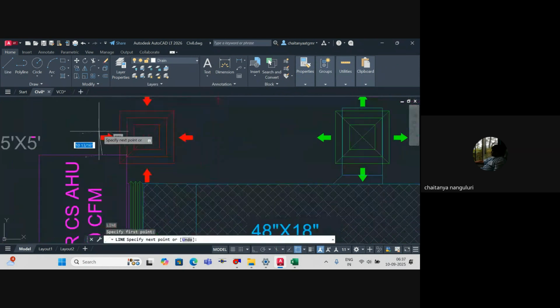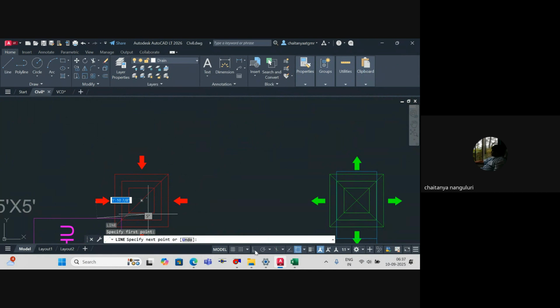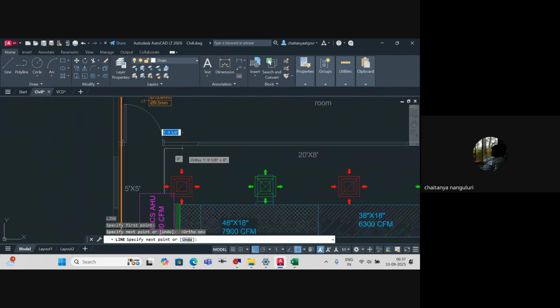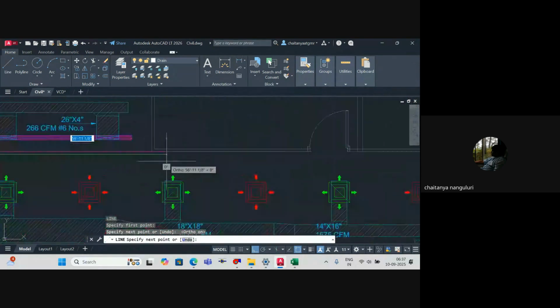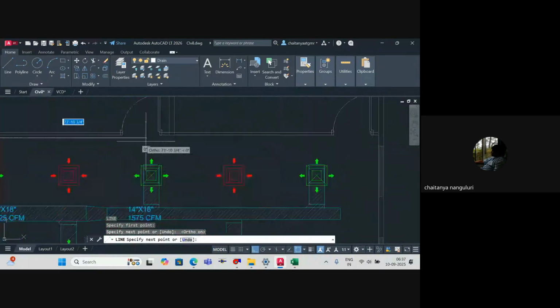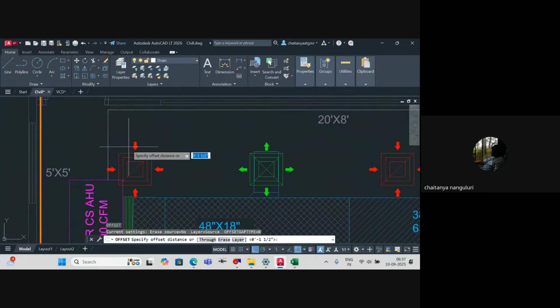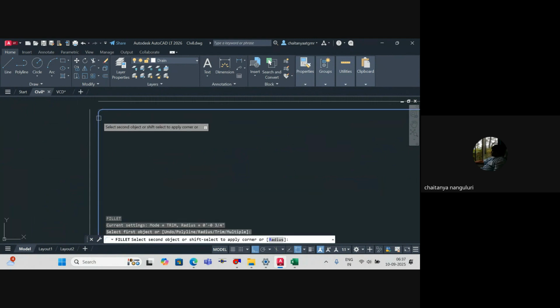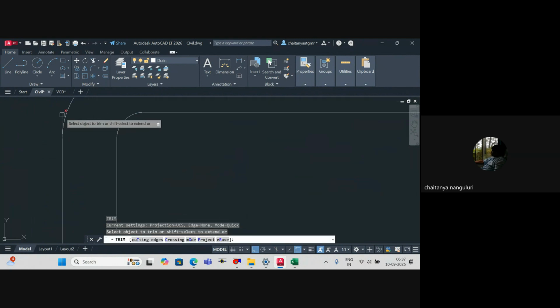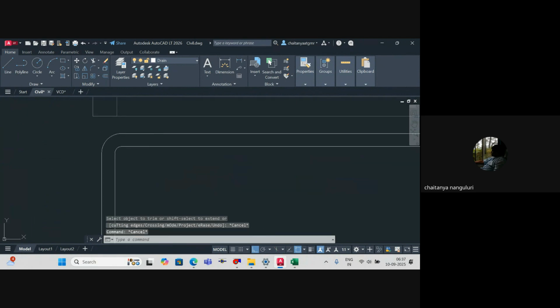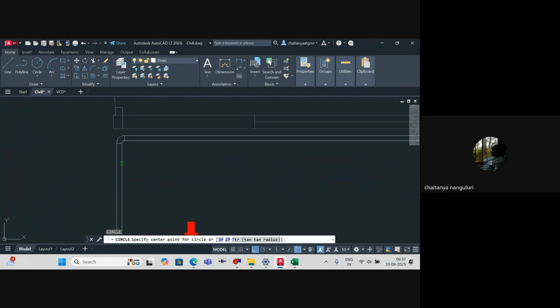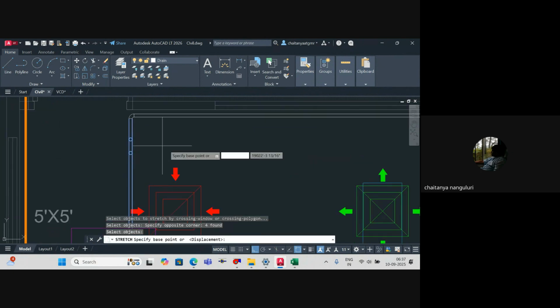The diameter of the pipe we can go is this one. Let's say, just a sec, I'll write it straight away. Let's say this is my toilet. I wanted to provide it to the female toilet over here. Offset 32, so 1.5 inches. Probably I'm using a U trap over here. That's the reason I just showed it like this.